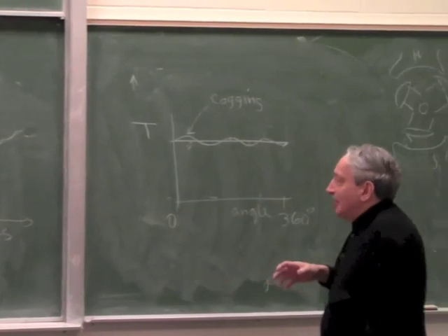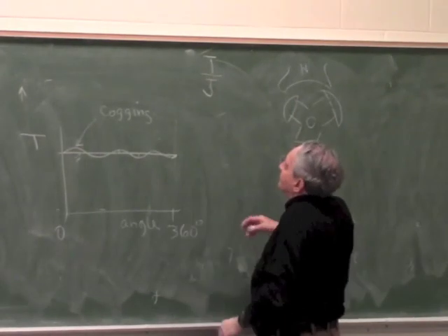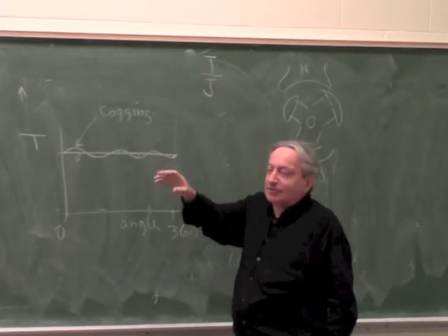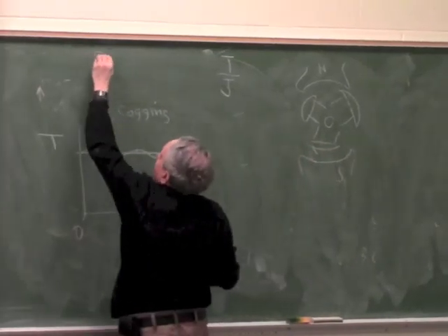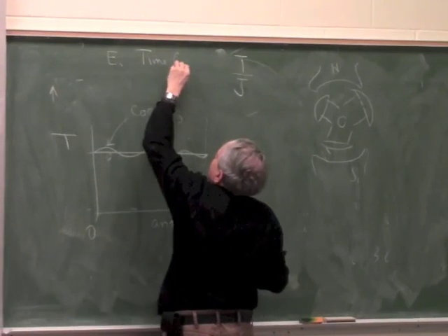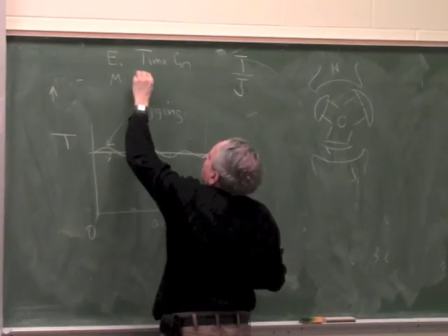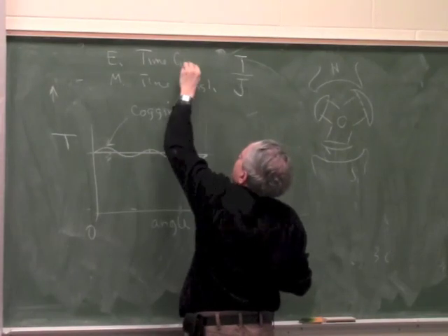So in a spec of a servo motor, there is a torque to inertia ratio. Sometimes it's given as a time constant. Sometimes it's not given as this, but it says electrical time constant, and it says mechanical time constant. Okay?